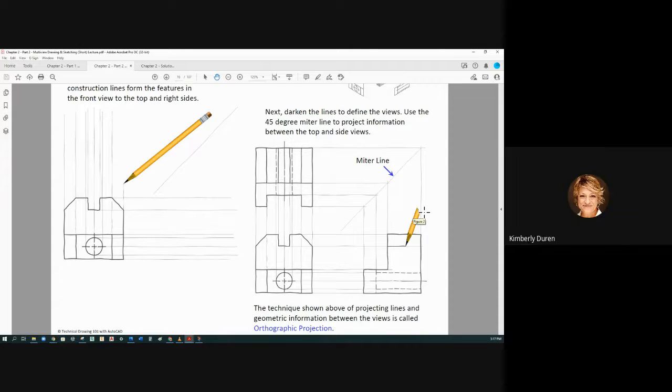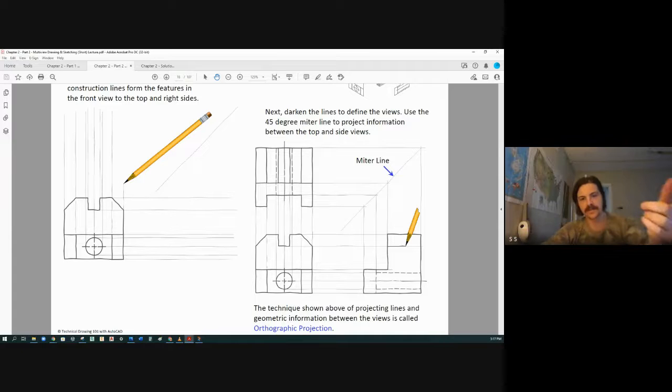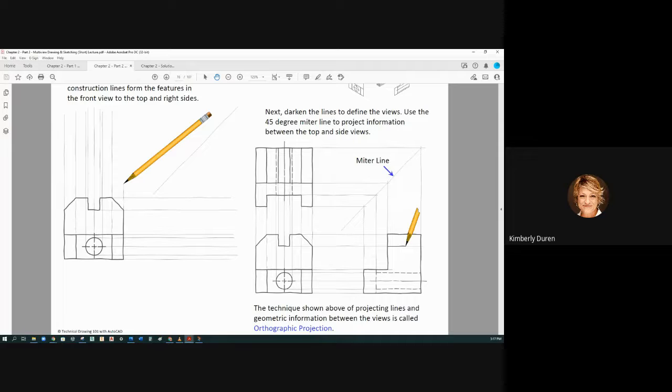Okay, now, in AutoCAD, you could actually use construction lines, or you can just hover over this and drag it out in Object Snap Tracking, and click to start and click to finish. You don't have to draw lines like this. But you would do the same thing if you're going to turn in some work for a customer. You'd make a box first and then... Yeah, and you want to make all those super light, you guys. The box, the miter line, and these projected lines, you want to make so light that you don't have to clean them up later.